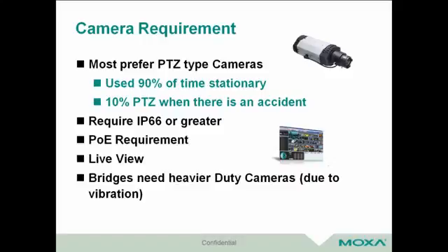One thing that I did notice is when you're putting these cameras outside in the field there's a lot of shock and vibration. There are different applications, and you really want to focus on those certifications, because even though you're getting a camera at a very low price, you want to make sure that the camera will actually last. In some cases, you have a camera fall apart because it's unable to take those vibrations. So make sure that you focus on the certifications that apply to the application so that you don't have a faulty camera within 6 months. You want it to last the lifespan you expect, 5 to 10 years.